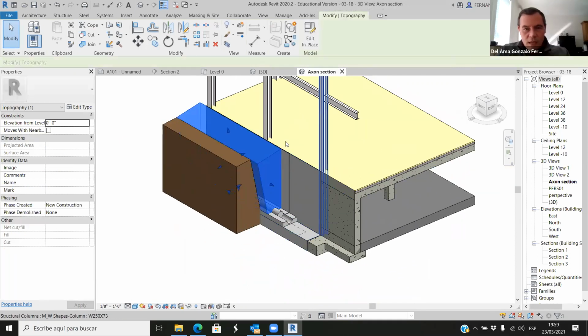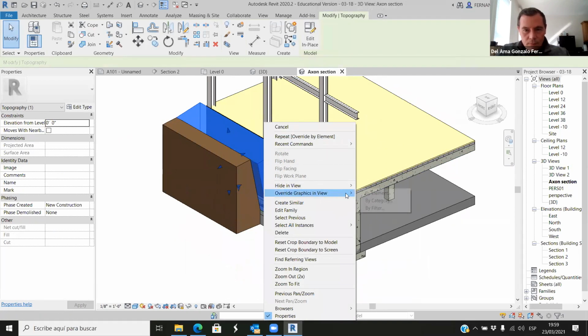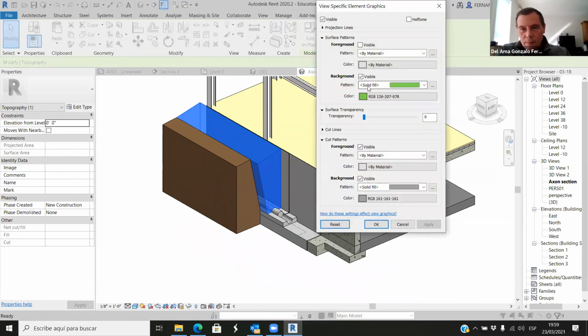Anyway, sometimes, if you want to change the color, make sure that it's always a solid fill. And if you're working with this architecture component by extrusion, if it's not a section, I think you have to work with the surface pattern. If you are working with a section, then you have to work with the cut patterns. Anyway, if you want everything to be the same, just change to the same color all these 4 components, and eventually it will work. Okay.